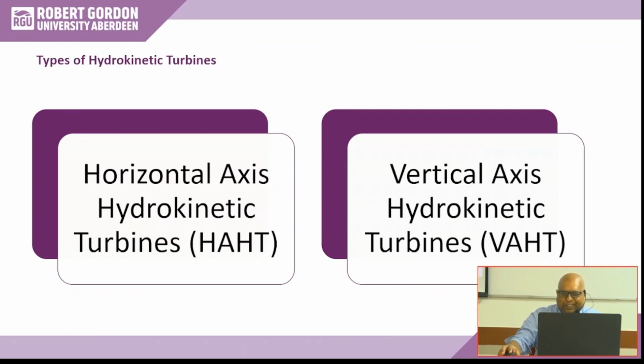Okay, you want to decide later after doing all sorts of analysis. But you may have a personal preference, right? Like Mahesh said, he's looking for a horizontal axis turbine, and you also said horizontal axis turbine, but nobody for vertical axis turbine. Yeah, I will go for vertical axis turbine because it's bidirectional, number one, and you can also put the generator and other things outside the water. Okay.